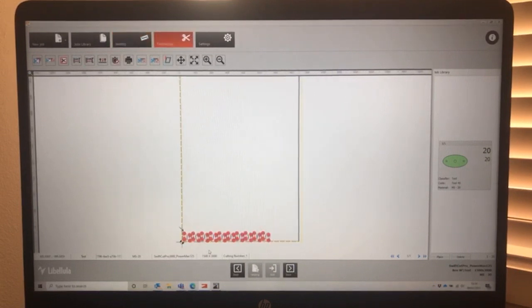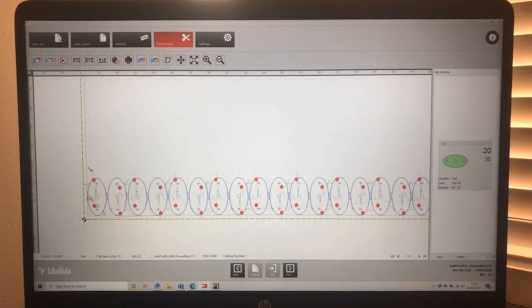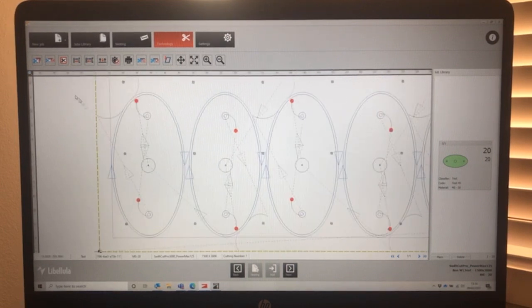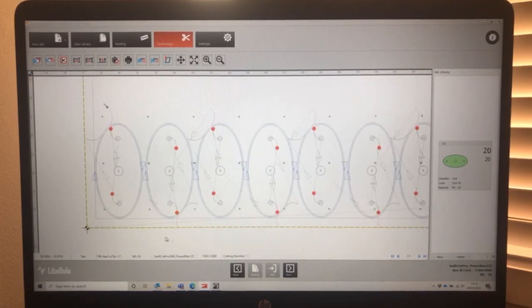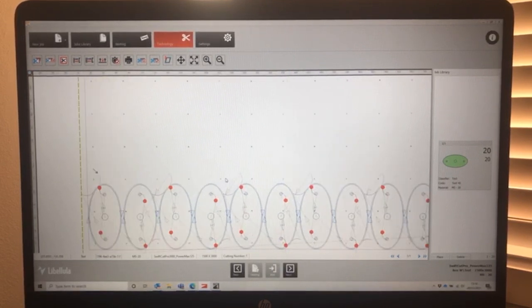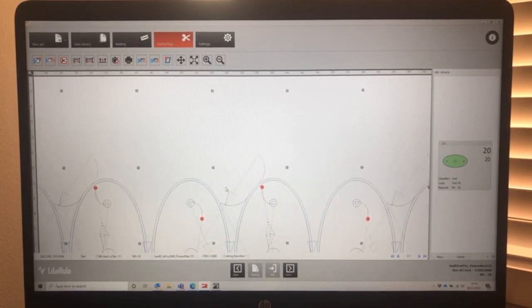Again, this is saving information back to the parts, and it will look at the nesting and then look at the tooling. So you can see, and I'll zoom in on a certain side here, with regards to the externals and the holes, because we've set this to center pierce, it doesn't need a lead in and lead out. The holes here and the external parts of the profiles have lead ins and lead outs applied to them. These are automatically generated based on the information that is built into the system, but you don't necessarily have to agree. Not only that, you may need to move them just because you know what the component's going to be used for afterwards, not all the time.